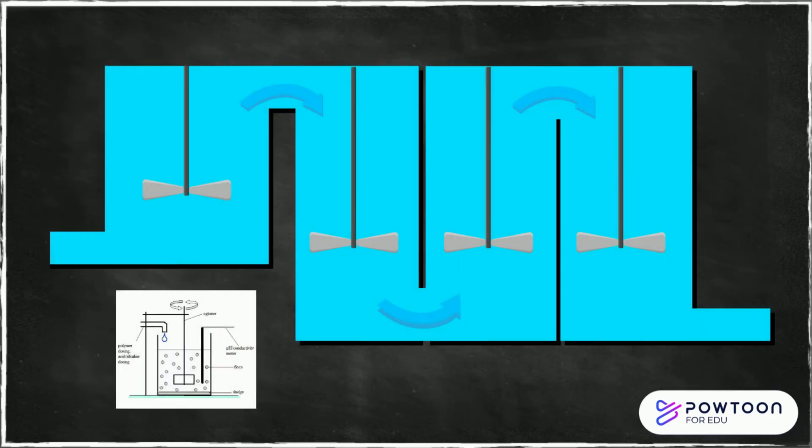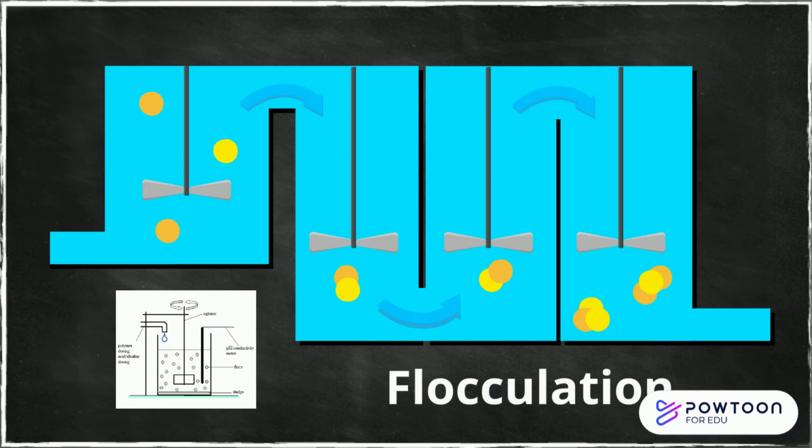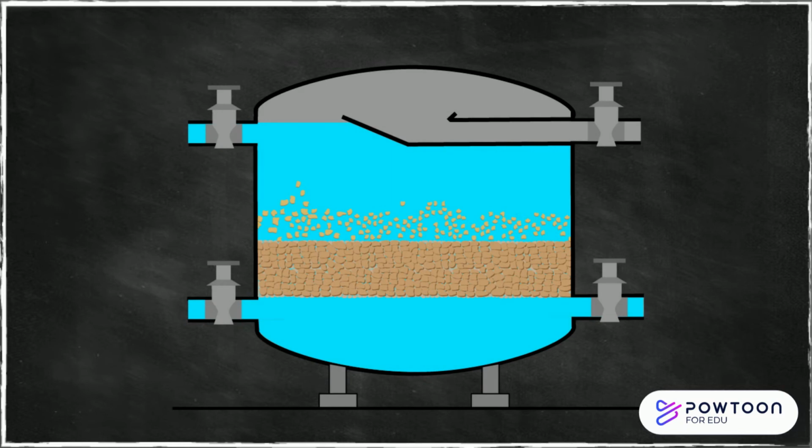After the coagulant is added, rapid mixing takes place to assist the particles in meeting and therefore clumping together, which is known as flocculation. Heavy clumped particles are known as floc. These larger and heavy particles can now be removed by sedimentation or filtration.